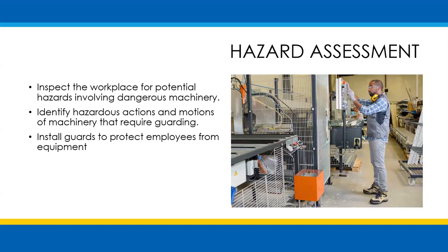Conduct a hazard assessment in your workplace. Inspect the workplace for potential hazards involving dangerous machinery. Identify hazardous actions and motions of machinery that require guarding. Install guards to protect employees from equipment.